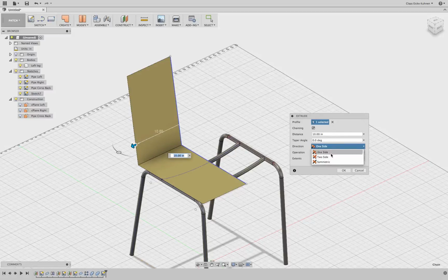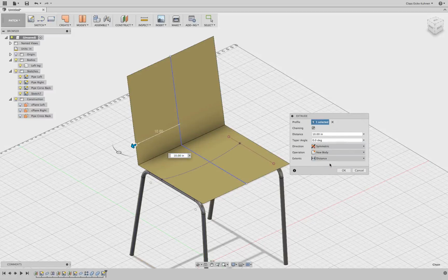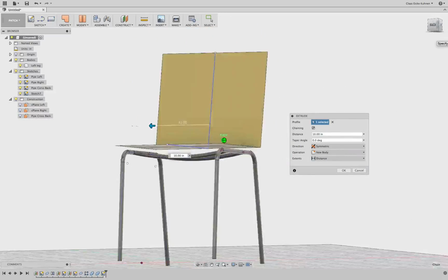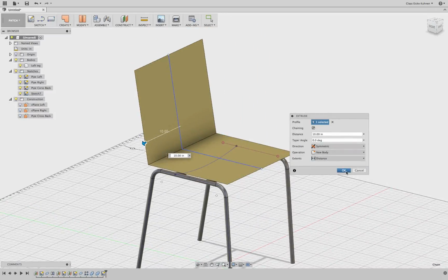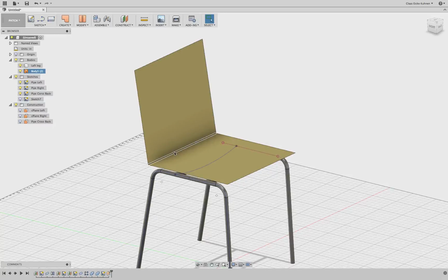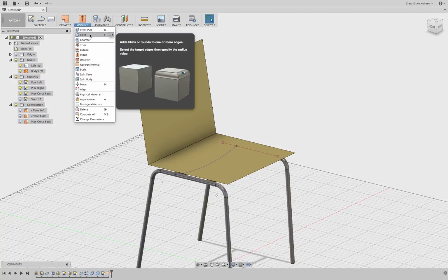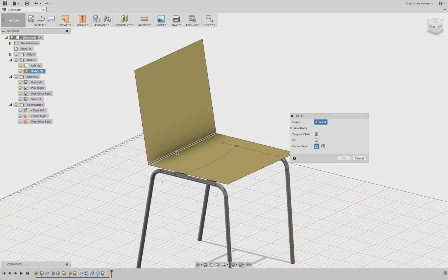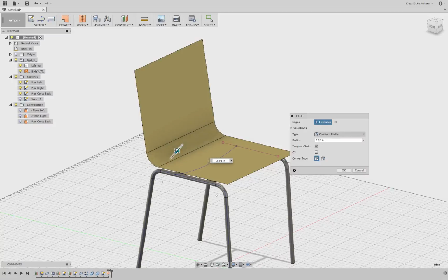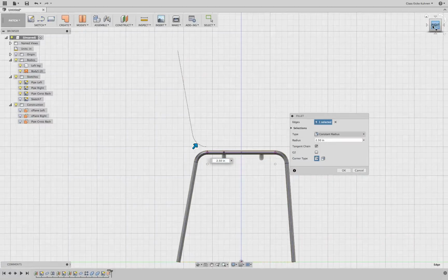When we go to direction, we can say symmetry or symmetric, and then it extrudes each side. Nice. Then I can click OK. You see here we have a very sharp edge, not very nice to sit on, no problem. I can easily chamfer or fillet this edge. Again, you see I keep the sketch very basic and then do other details later in the surface tools.